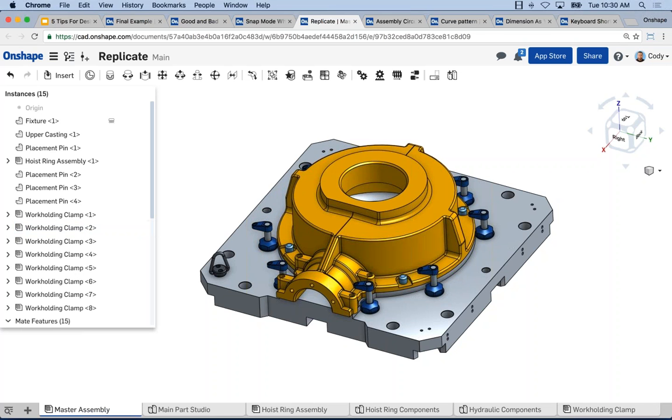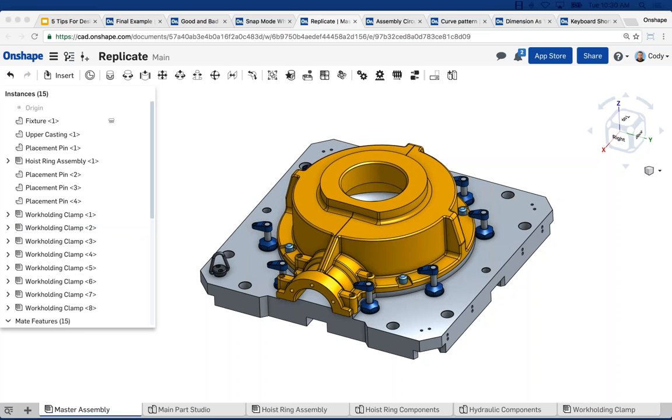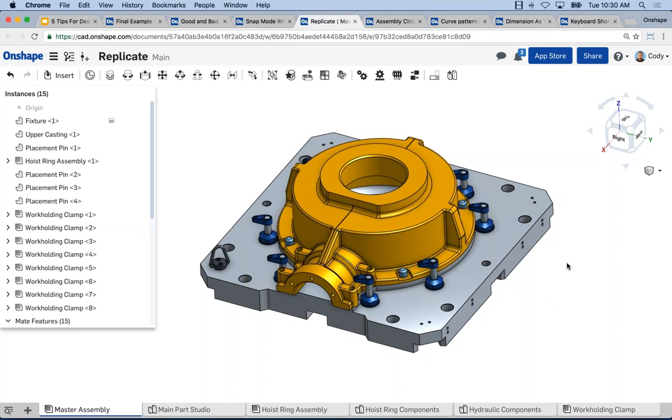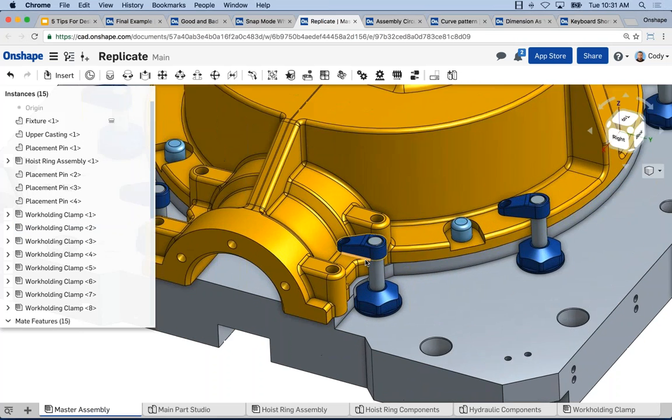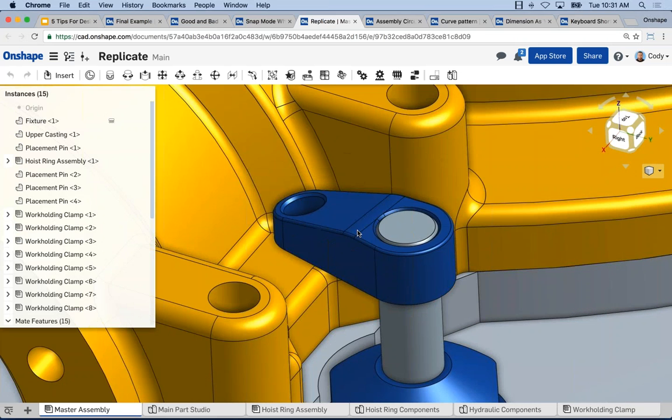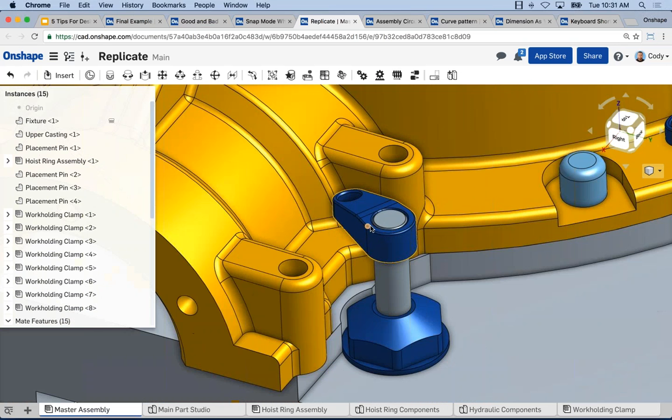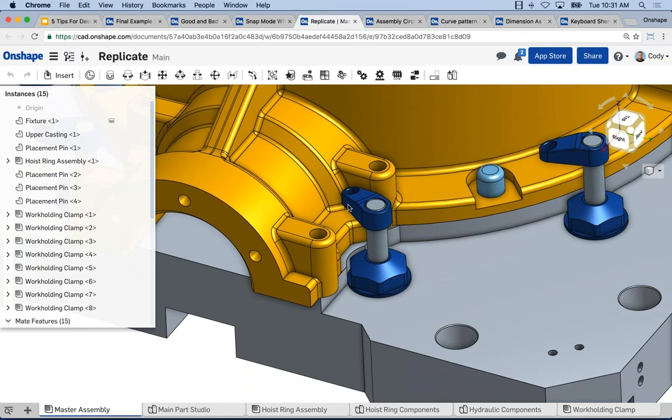Okay, in your example, how is the retention bolt head direction set? Forgive me, if you're referring to the clamp arm, I'm not sure that you are, so forgive me if that's not right. It's not set. It's free floating. This clamp is free to swing in and out because that's what you would need to get the part in and out of the clamp.